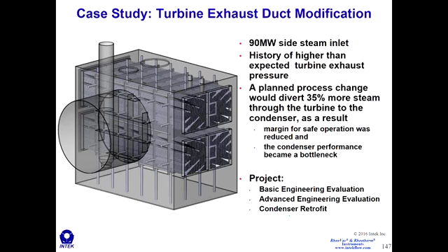This is that case study that I talked about earlier, and this is what I really wanted to show, something different. We did address some air binding in this condenser, but there was another aspect of this condenser that we found by putting this instrumentation on the condenser. We found an opportunity to reduce the turbine exhaust pressure in this particular condenser.